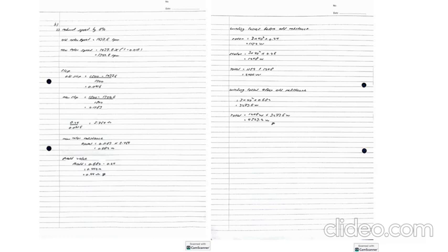Okay, for winding losses after adding resistance, we need to use the R total, which is 0.682, with the same formula, 3 times 40 squared times the new R total, which is 0.682. So we got around 3273.6 watt. This is for the rotor.